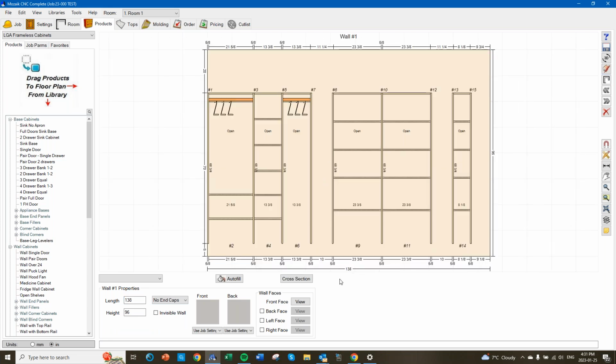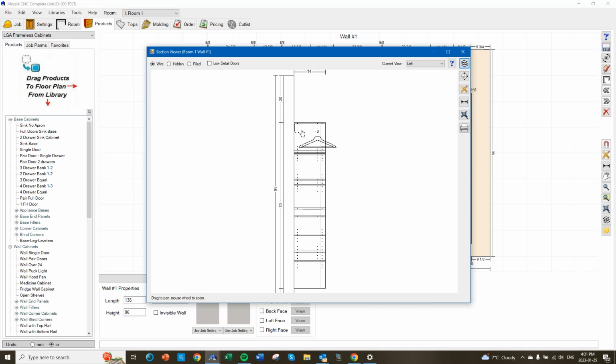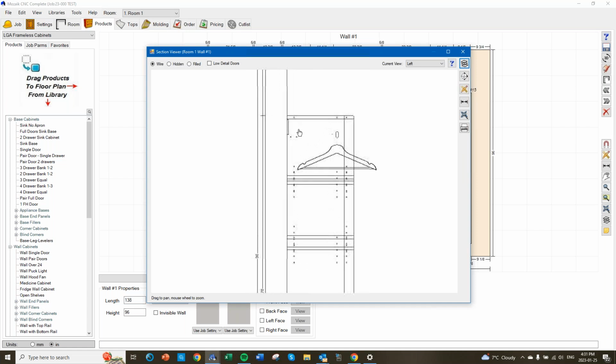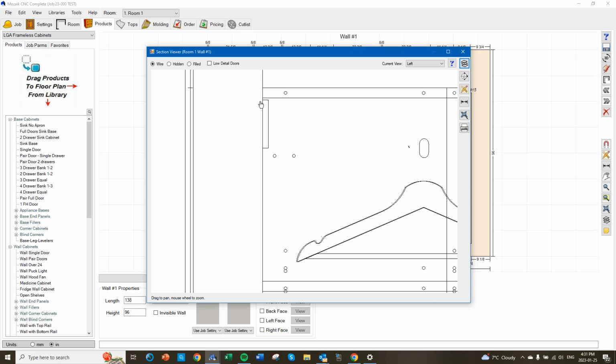Okay. First, the cutting, the notch at the back, that little notch is too close to the top. And then I want this going down here to meet those 2 holes here. These 2 holes are counting from this edge and not from this edge. So when I put the bracket on, it comes flush out. So we need to take these holes and shift them in this direction, the equivalent of whatever width that is.